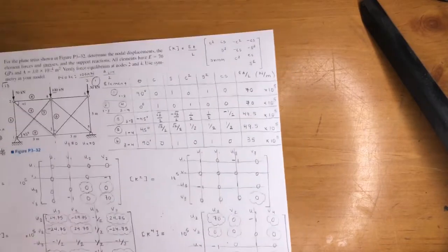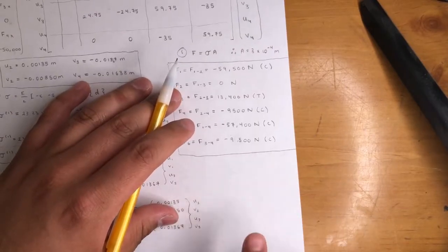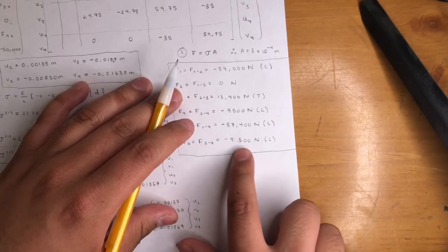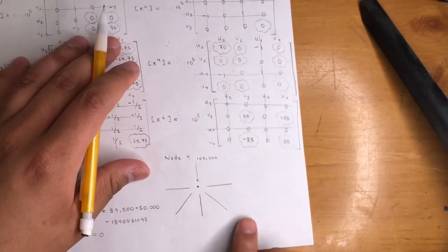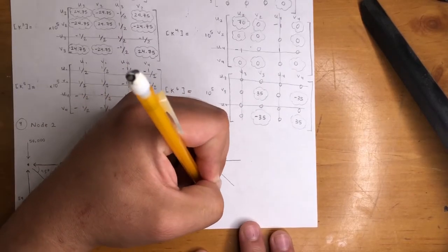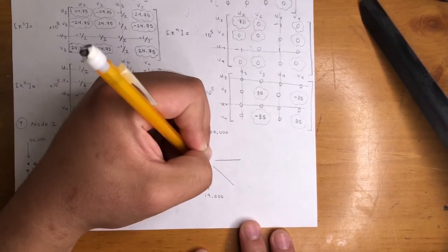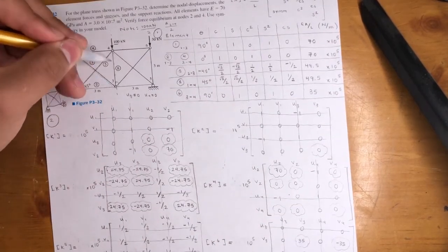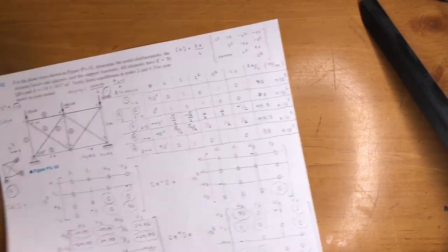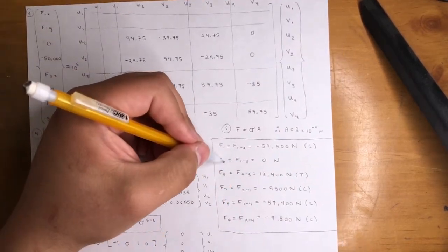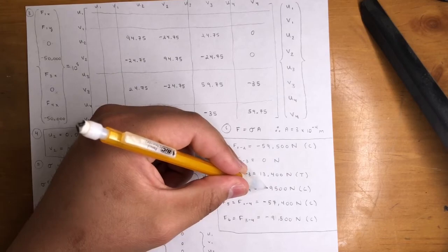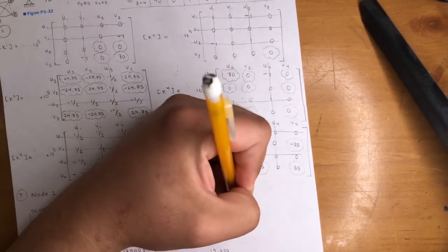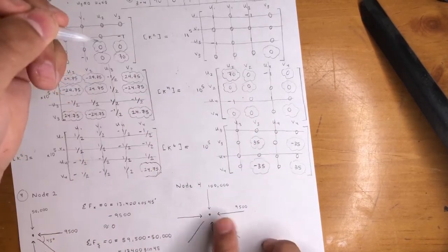But when you do it here, it's negative 9,500, so that means it's pointing into it, right? From node 3 to 4, it's pointing into the node, 9,500. But when you take into account both sides, you'll get a 19,000, and it's going in. Okay, so we got these two. Now, that was from 3 to 4, so now we're going from 2 to 4. That is this one, negative 9,500. So from both sides, it's pointing in. Negative 9,500. Well, it becomes positive because it's pointing in now.